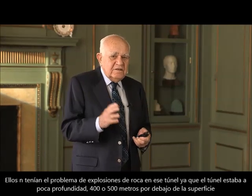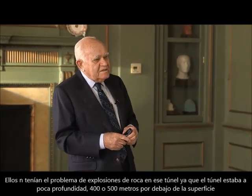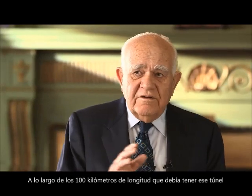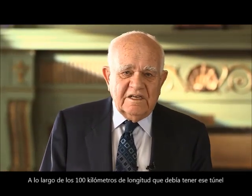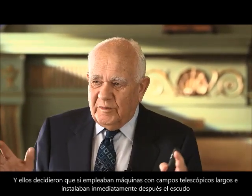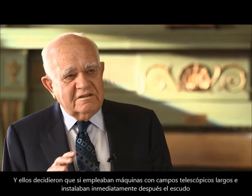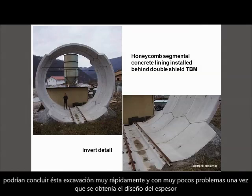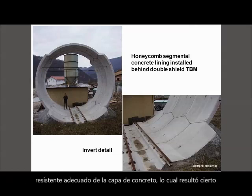The tunnel was relatively shallow, perhaps maximum depth of 400 or 500 meters, going through a variety of rocks. And what they did was they assessed the conditions along the 100 kilometers of tunnel that had to be built, and they decided that if they used machines with long telescopic shields, and they installed immediately behind them shield concrete linings of the type illustrated here, they could go right through this at very high speed with minimal problems. And provided the design of the thickness and the strength of the concrete lining is adequate, that proved to be the case.